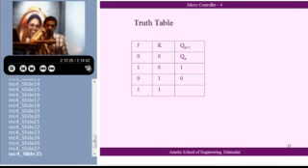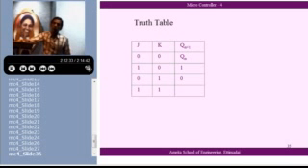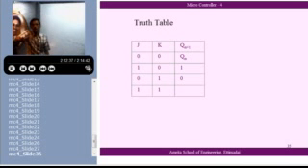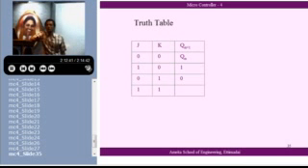Now we will see how to make use of the JK flip-flop for various operations. So I've got here 3 modes of operation for the JK flip-flop. In one mode, the old value is retained. In another mode, the present state is decided exclusively by the J and K values, whether it is 1, 0 or 0, 1. In the third mode, where J and K both are 1, the flip-flop will just change its state. There are 3 modes of working of the JK flip-flop.